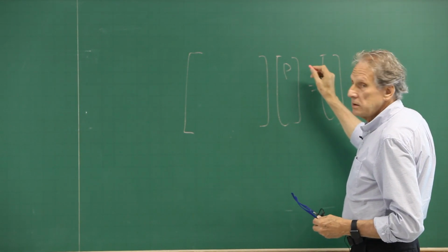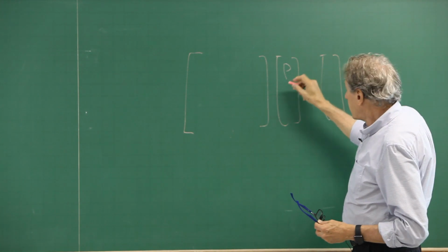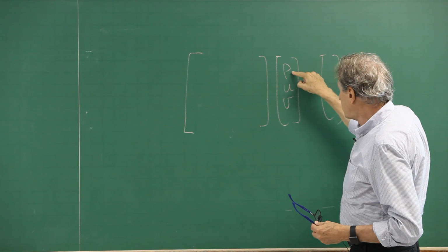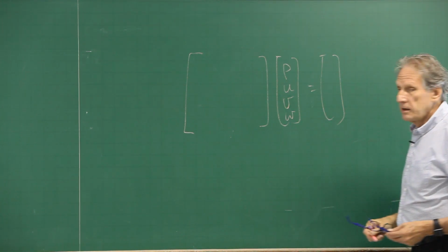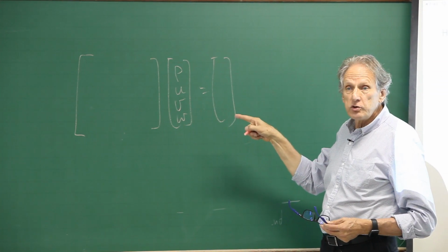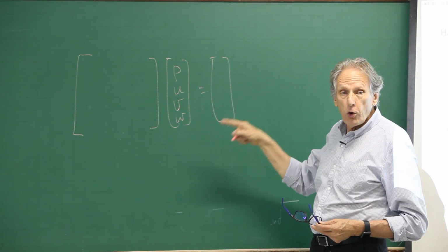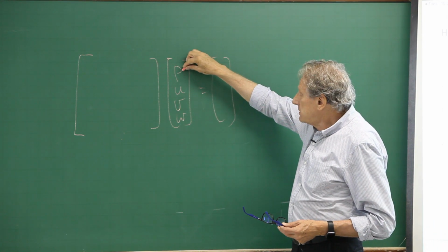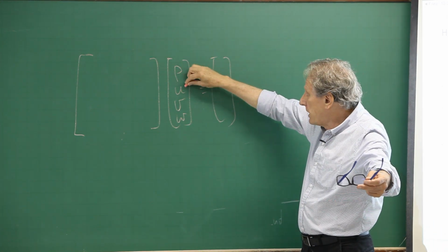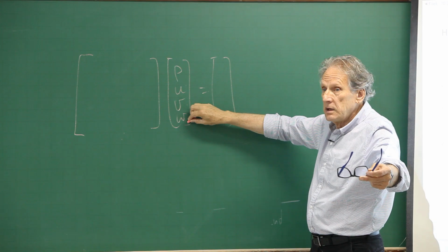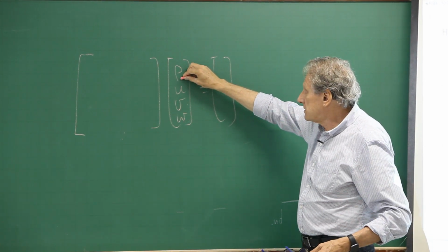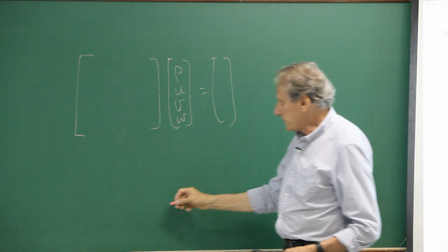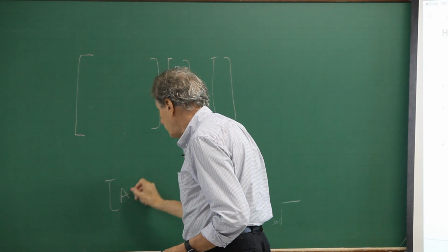It is rho, U, V, and W. This is what you solve simultaneously when the flow is compressible. You take this from the mass conservation, momentum. And then when you solve that, of course you are going to solve temperature also. Some way, you're going to solve the temperature.